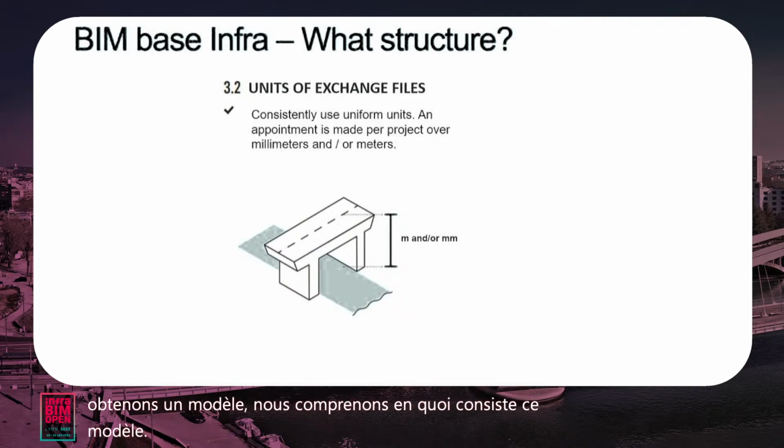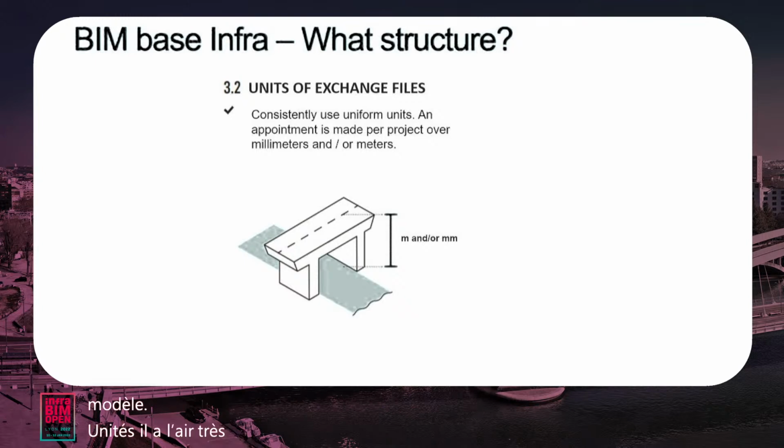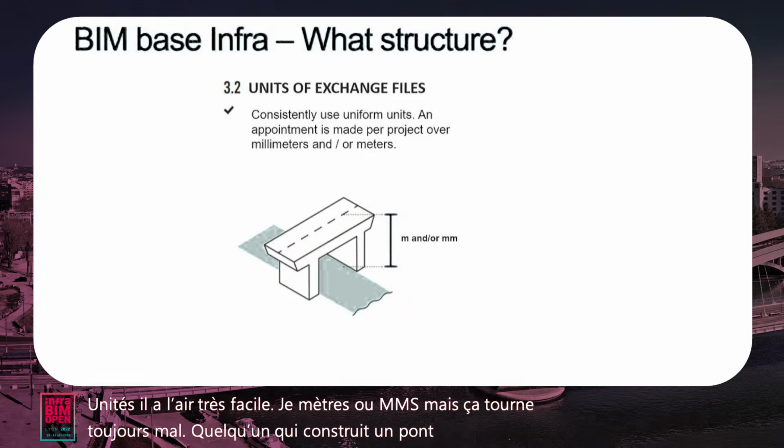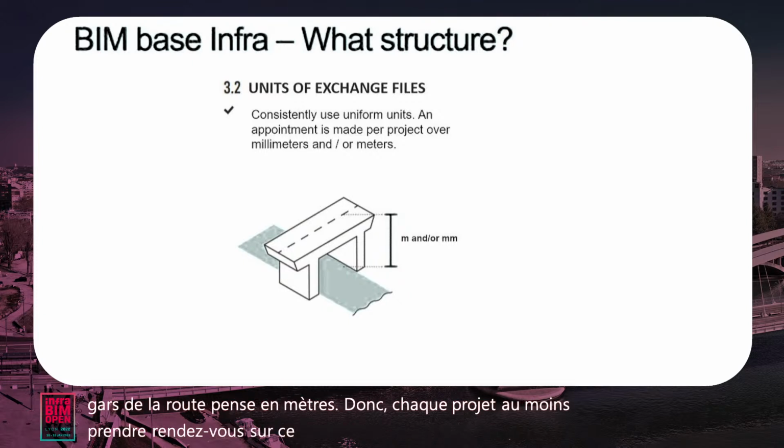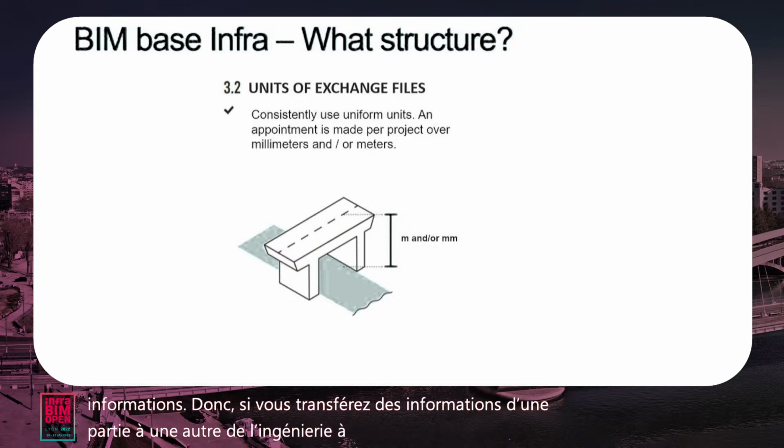Units, yeah, it looks very easy, meters or millimeters, but it still goes wrong. Somebody who's building a bridge thinks in millimeters, a road guy thinks in meters. So every project, at least, make an appointment about what units you transfer your information in. So if you transfer information from one party to another, from engineering to contractor to supplier, make agreements on millimeters or meters.